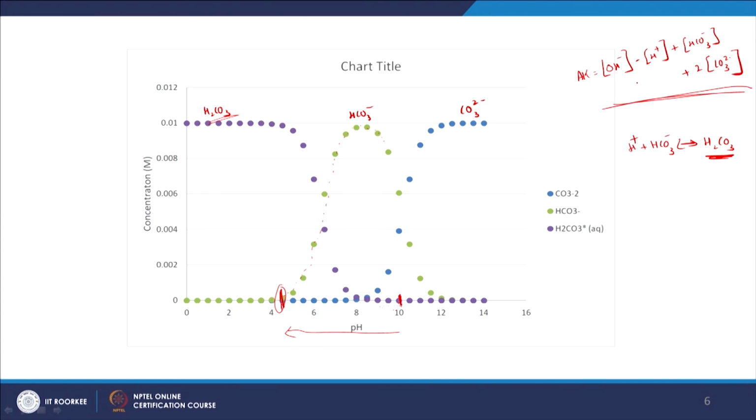So, these are the concentrations at pH 10. You can calculate the relevant concentrations and plug them in, or you can also titrate and then calculate. Because you know how to use Visual MINTEQ or such, you can calculate the equilibrium concentrations of HCO3 minus and CO3 2 minus from it and just plug them in, or you can go back to the lab and titrate and look at the amount of acid required to reduce the pH of the solution to the H2CO3 equivalence point, which is 4.5.